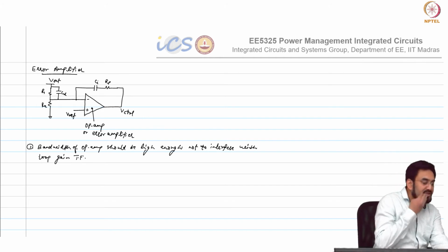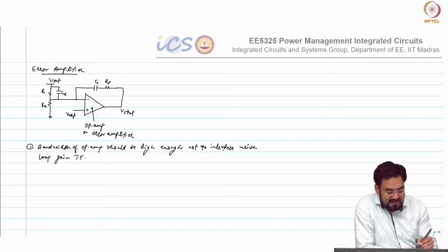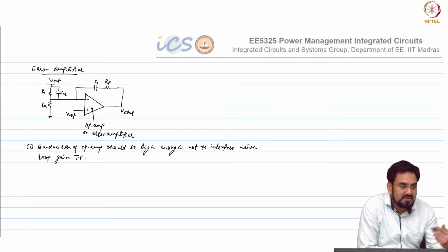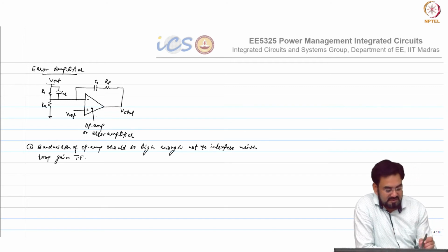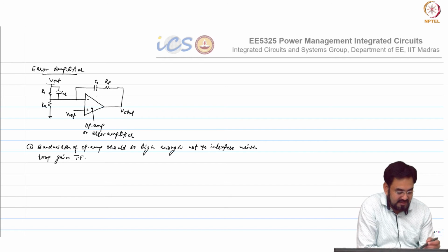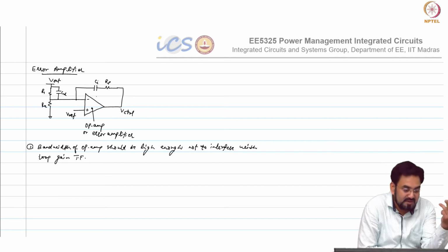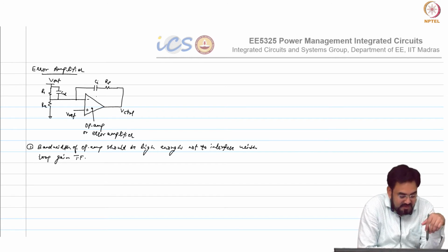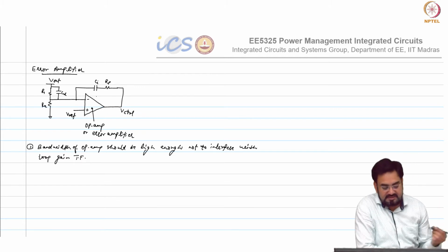So what we want, we don't want an additional pole from your op amp, because here we are introducing an integrator with 2 zeros, and then on top of that we put 2 more poles, if you remember, high frequency poles due to noise reasons.